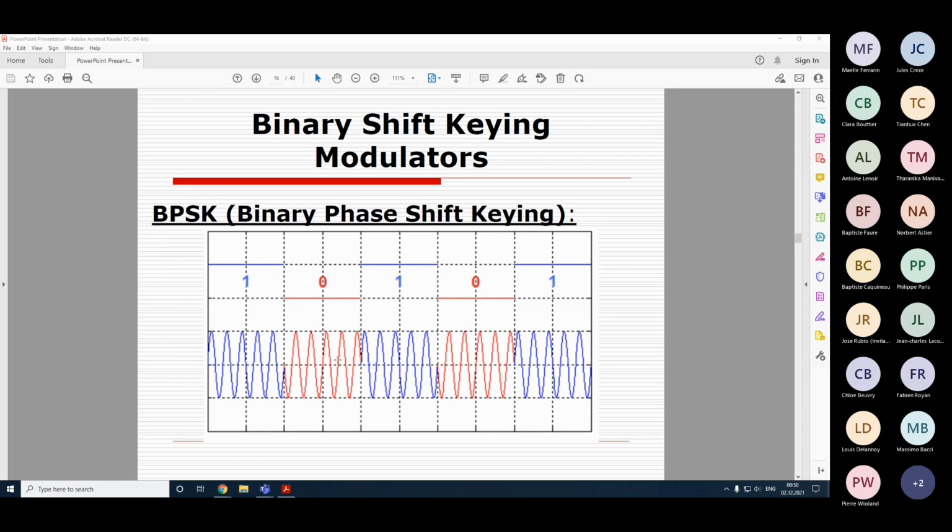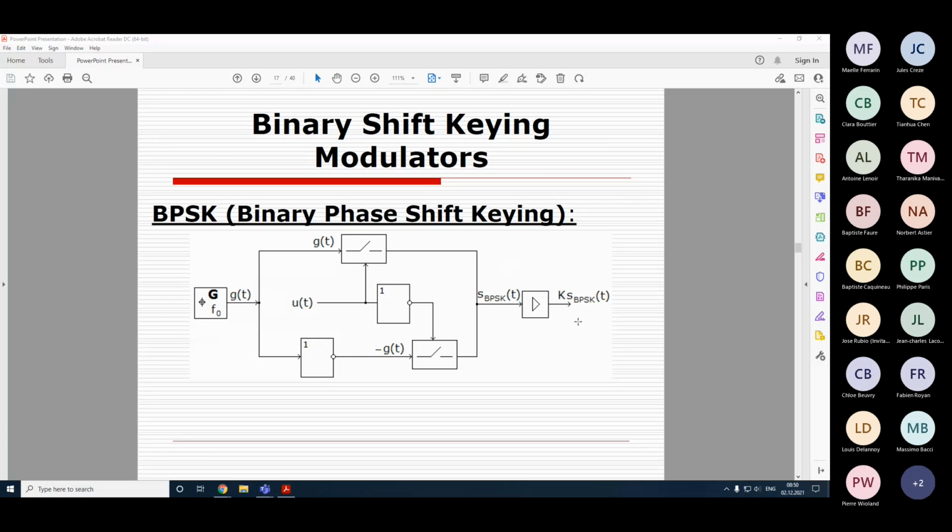So the signal then looks like these phase changes. Yes. So basically, the information, are we sending 1 or 0, is hidden in this change of the sine wave phase, and accordingly we will have to design some receiver which will be able to read this information from this received signal. But before that, let us see how we generate this signal.